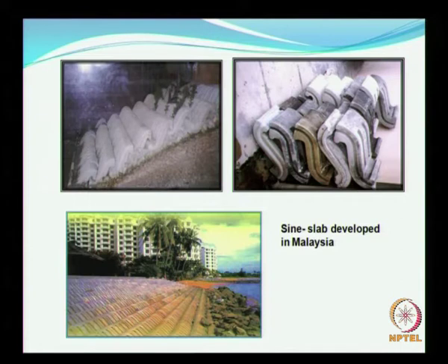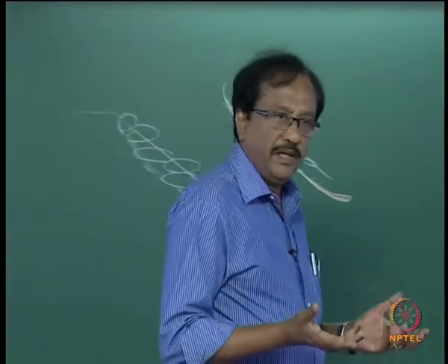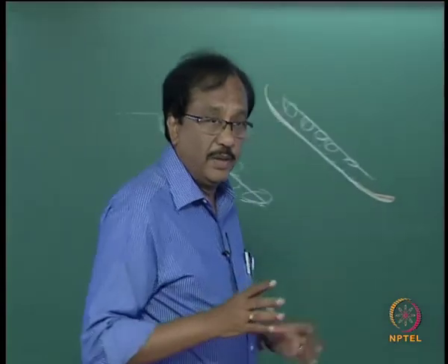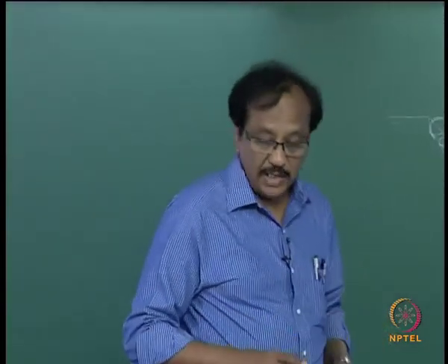Now you look at this, it gives a nice aesthetic point of view, but also you look at these projections. When you have a lot of projections, it is going to offer a lot of friction. When you have more friction, the energy is getting dissipated, that is the advantage. And added to this, if you have some kind of plantations along with this kind of slope, this could become a very good protection measure, but then you need to look at the cost implication and also the importance of the project.